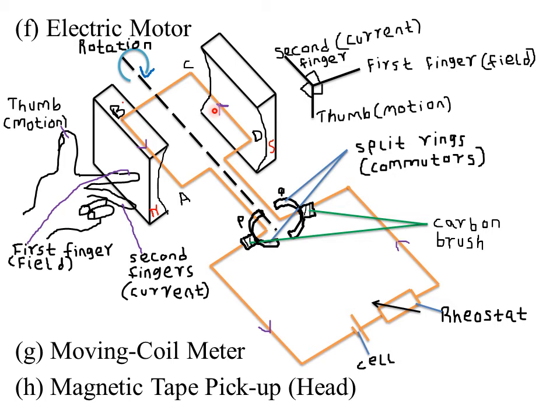So we've said that since the current in both sides of the coil is the same, the forces are equal and opposite. These forces cause the coil to rotate in the clockwise direction until it reaches its vertical position with side AB up and CD down. So CD moves down and of course AB up.